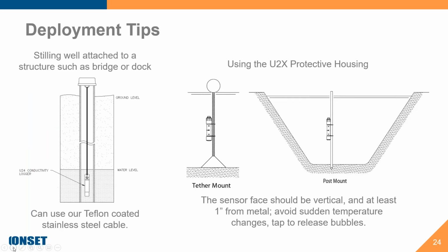Here's a couple other methods for designing your mountings. Stilling wells, again, can be some slotted PVC pipe. They don't always have to be completely vertical, but you want your data logger itself in water and suspending it to the top so you can access it again. Using the protective housing, they're anchored onto rebar. Again, you have water flow, you could have debris, anything that can help protect that logger, because keep in mind, you have a battery, you have electronics inside. These are quite rugged and durable. We experience long life from these, but again, taking just some kind of general good practices for mounting these to find them again is always a good idea.